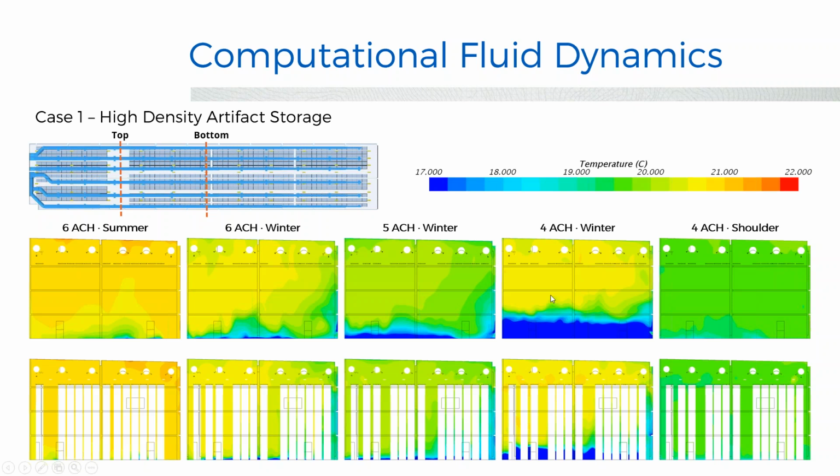An important point to note about these simulation results is they are steady state results. We are taking all our environmental conditions and our operating conditions and then running the simulation until the conditions stop changing. And then we get one image of what will happen. As this is an extreme winter design case, we're setting it up at nighttime so there's no solar benefits. We are putting in a cold outdoor temperature and then basically leaving it, you can picture, for an infinite amount of time, although it's not an infinite amount of time. It's just until we're happy that we've reached one final answer. So it's a very extreme case, but it gives us an idea of where things will tend in those conditions.